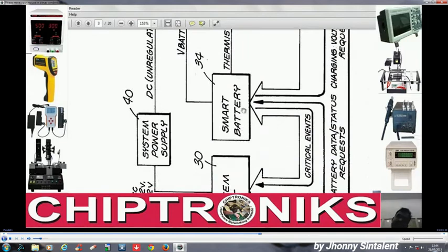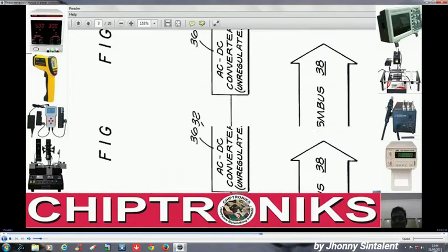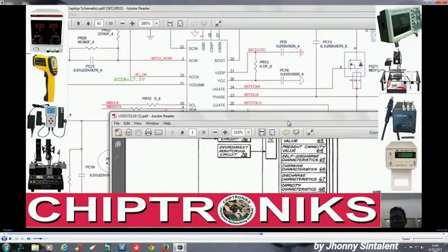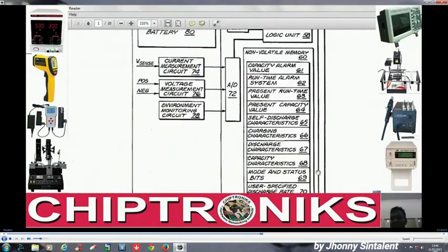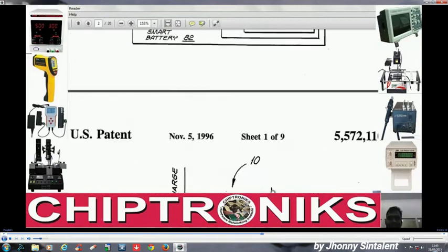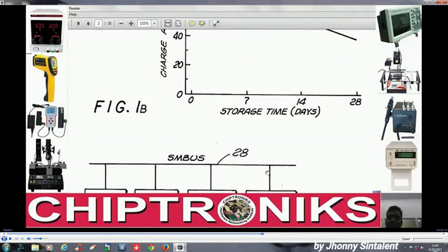If the capacity of the smart battery has reached its critical point, then it will generate a critical event signal to the IO controller through SM bus, right? Here we'll come again and see, because these are very important concepts and we must understand these things very smoothly. And if you feel any problems, you should just email me. Okay, this is SM bus, data and clock. So you can see how they are communicating with each other.